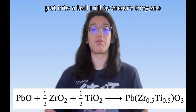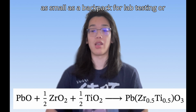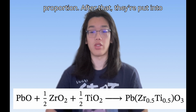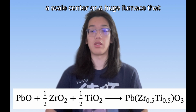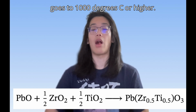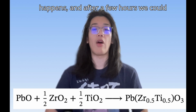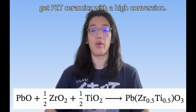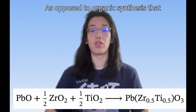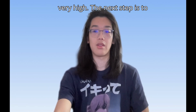Then the mixture is put into a ball mill to ensure they are homogeneously mixed. A ball mill can be as small as a backpack for lab testing or as large as a truck for industrial production. After that, they are put into a calciner, or a huge furnace, that goes to 1000 degrees C or higher. The furnace is where the reaction happens, and after a few hours we get PZT ceramics with a high conversion. As opposed to organic synthesis that needs strong driving forces, the yield is very high.